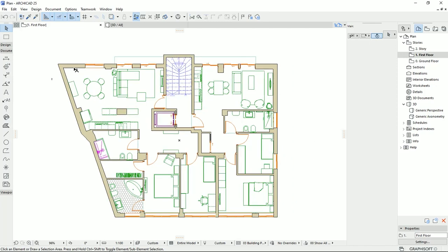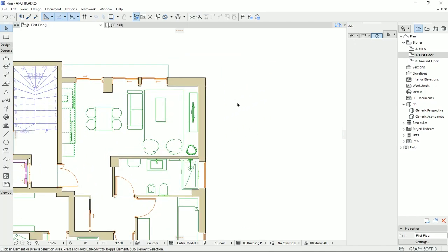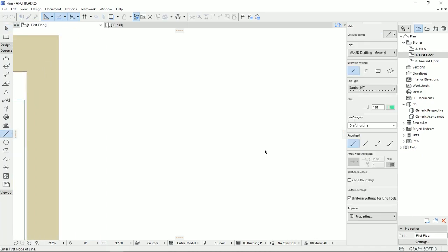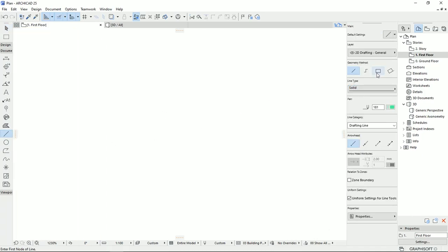To start drawing the cornice or the skirting for the walls, first we need to design the profile that we want to use as these profiles. So first I'm gonna design a skirting profile. So I know that I need an area of, for example, 0.03 and with the height of 0.12. Then on this rectangle, I'm gonna draw some lines to use it as the profile.